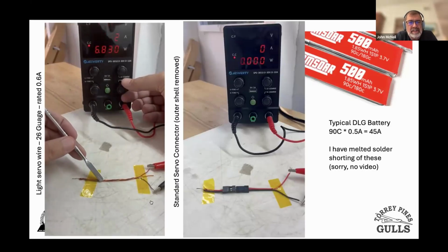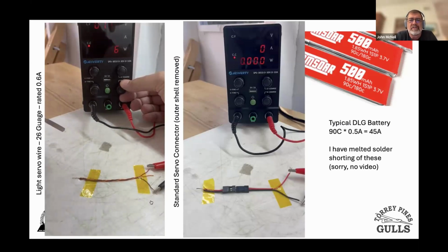Now the wire is going soft at 6 amps, and I'm going to stop playing with it and crank it up to 10. So this is way beyond what you're going to run with stalled servos in a dive on a hand launch glider, right? I'm not showing you this to say, go with microscopic 30 gauge wire, nor am I showing it to you to be alarmed. I'm just trying to build some intuition here. But just for fun, 10 amps just cooks the wire.